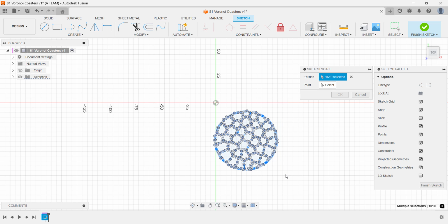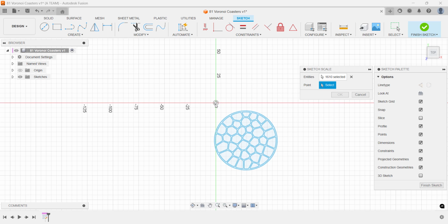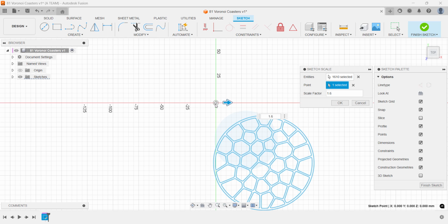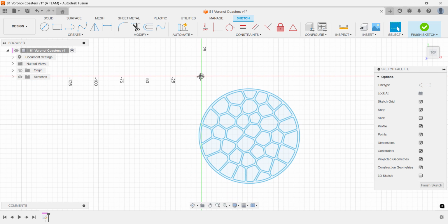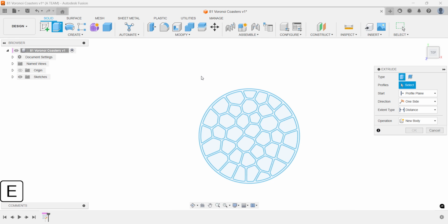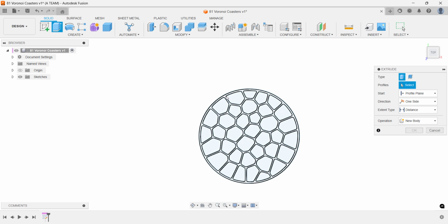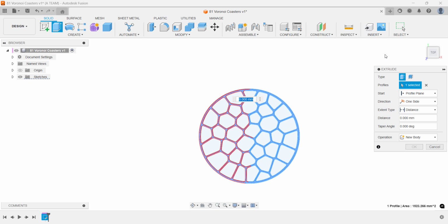The blue sketch color tells us the design isn't fully constrained. While full constraints are important in more complex projects with multiple parts, this is a simple one-part design. So to save time, I'll take a pragmatic approach and leave it unconstrained for now. By hitting E on the keyboard, you're doing two things at once: closing the contextual sketch environment and immediately opening the Extrude command.